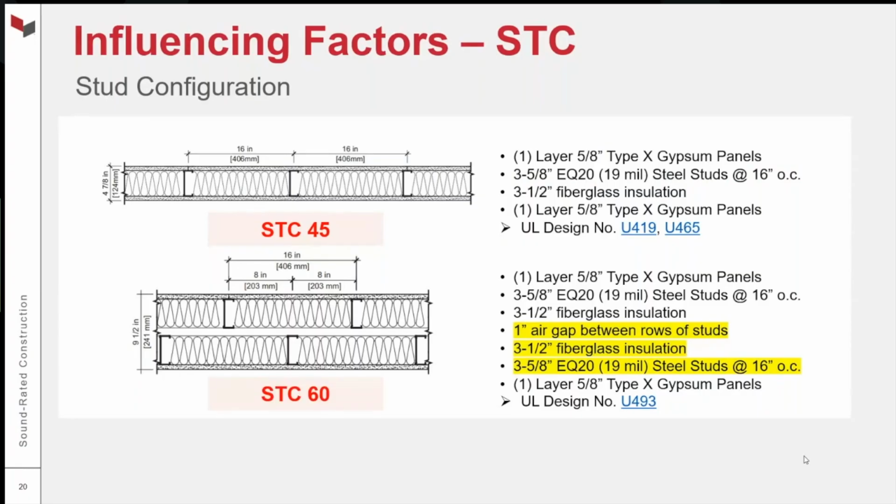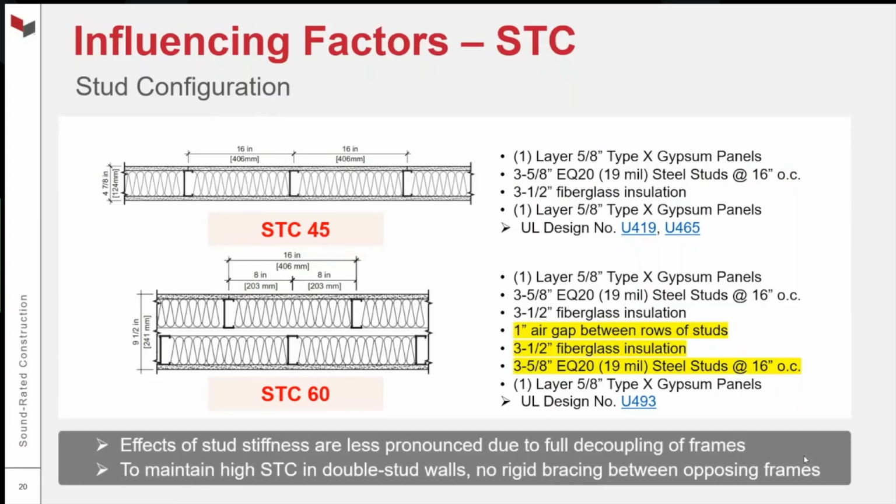Why? That's because you have 2 independent steel stud frames here, and so there's an extreme amount of decoupling. You've fully decoupled one side of the wall from the other, and that's really going to improve STC.